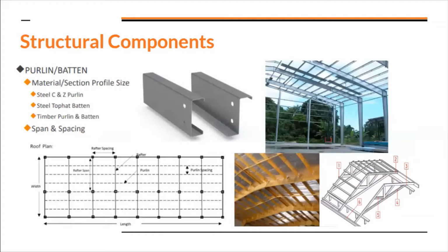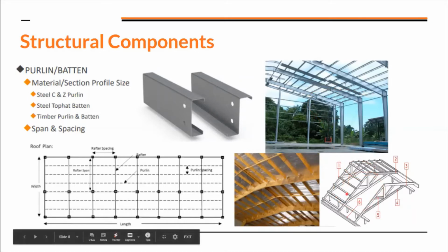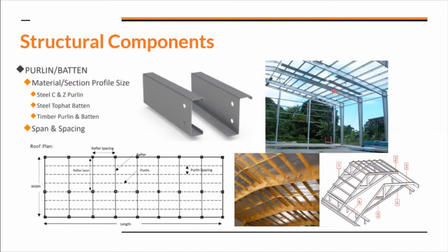So there's a few types of roofs you can see here. Basic roof systems are going to be either steel or timber. Both of them are made and assessed in the same way, but obviously the strengths are very different, which means that steel structures are usually quite large, and timber structures could be residential or home structures. And when we're looking at steel structures, the main components are these major elements, which are called rafters, and the minor elements that connect above them together are called purlins.